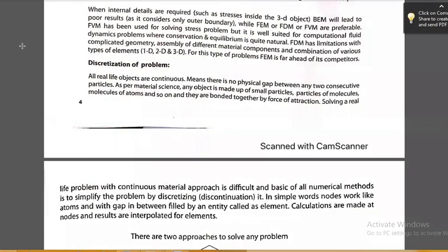What is an equilibrium position? What do you mean by equilibrium, or a stable condition or unstable condition? That also you should know. Equilibrium is the state of a system or body where, if we disturb it by an infinitesimal amount, meaning a small disturbance, it will regain its original position after the disturbance. Such a state is called the equilibrium state or equilibrium position.